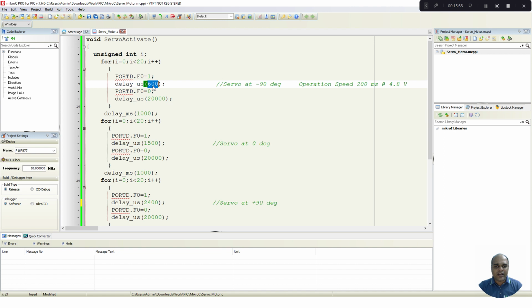Of the same 600 microsecond on time, I am going to send 20 pulses. Let us assume the servo motor captures the pulse 5 times. When it captures for the first time, it goes to that particular position. When it captures for the second time, the shaft is already in the desired position, so no correction takes place. So there is no harm in sending multiple pulses to a slow device, especially the servo motor. That is why we send multiple pulses to get the servo motor shaft to a particular position.